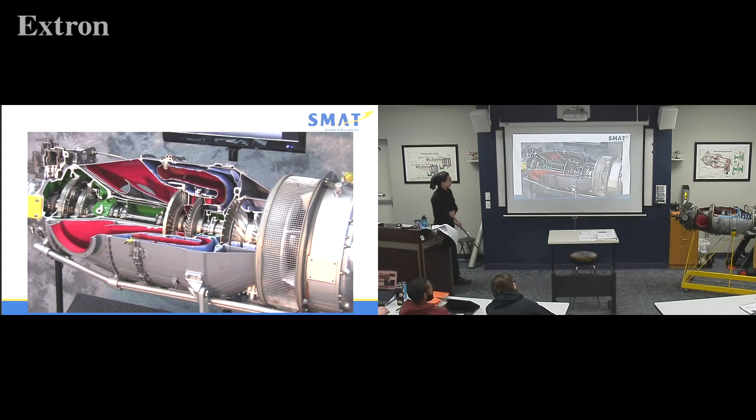It's kind of hard to see on this diagram, but compressor coming up to our burner, going onto our compressor turbine, and then there's no mechanical linkage. Air is going right onto our power turbine, and then out to exhaust.